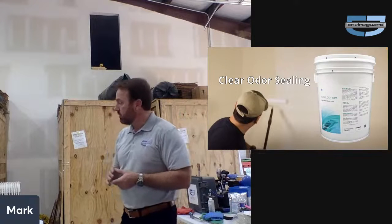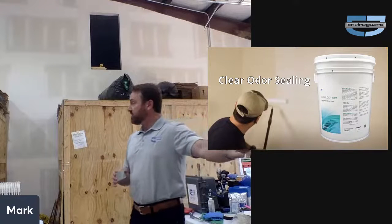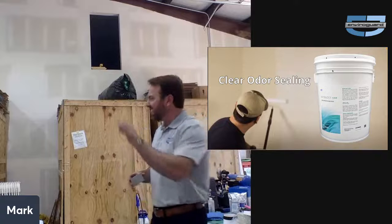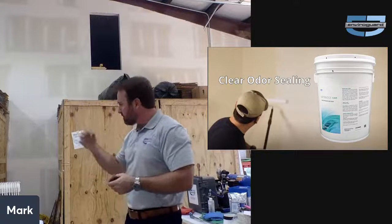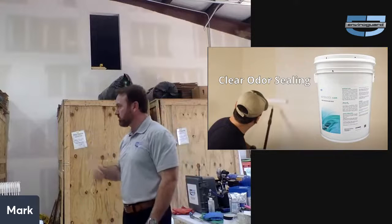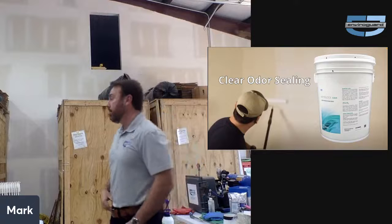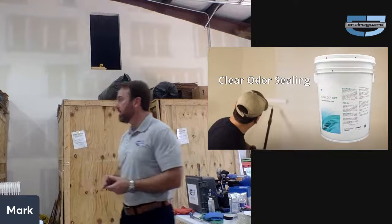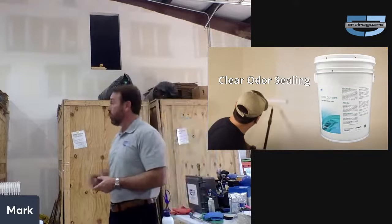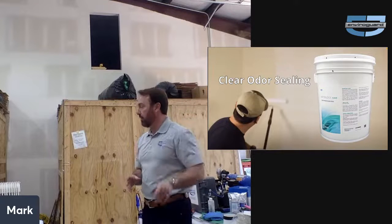Is it better if you roll that on or spray it? I sprayed it on and then back rolled it, right? Because if you don't back roll it, it's a little thinner, and it'll develop some drips and things like that. But it's very highly sprayable, so it's good to spray on and then back roll. Does it leave a glossy stain? No. You paint over it after it dries? Yes. Without priming it. Yep. Both products are self-priming.